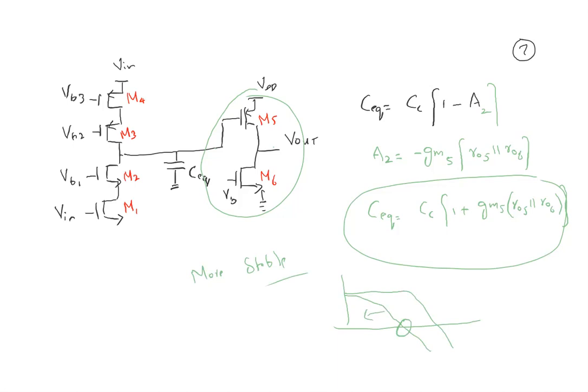Considering that the phase crossover frequency is not changed, if omega px is the same as old, and gx is lesser as compared to previously, it means the system is becoming more stable, or our phase margin is increased, or we can say that our response is now a more stable system as compared to the previous.